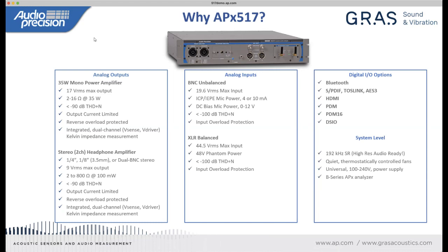So the key here is with the 517, we have as simple a physical configuration for this test as we can, since all of the peripheral devices, which are a source speaker, a measurement microphone, and then the actual PDM microphones under test, will just be connected directly to the front panel.